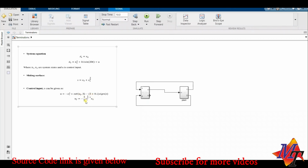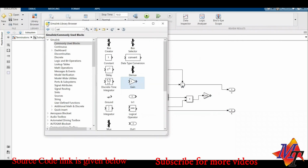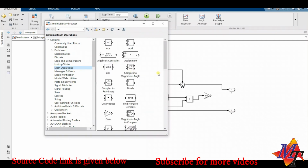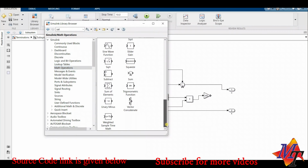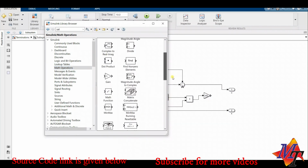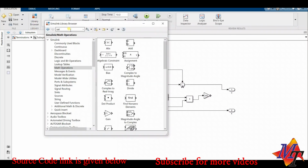So we have got here, and the last part is saturation of this, minus 3 by 5 x1 raised to the power 3 by 5 minus 1 x2. So we have taken minus 3 by 5 into x2 into x1 raised to the power 3 by 5 minus 1. We have to take saturation of it. So we'll pass it through a saturation function as well. For that we will go into math operations, that is saturation.